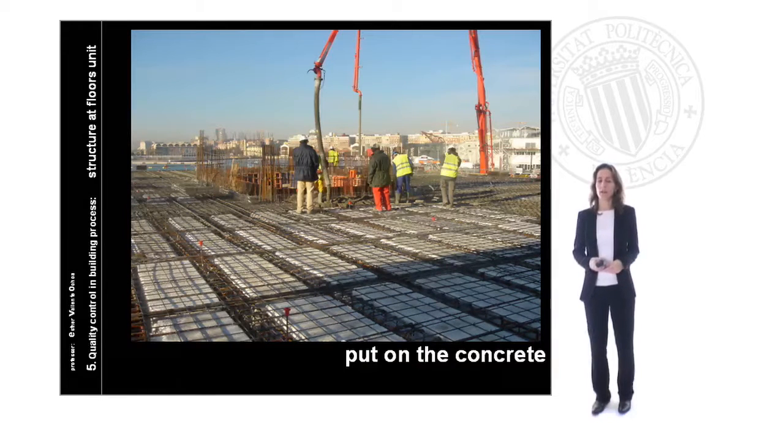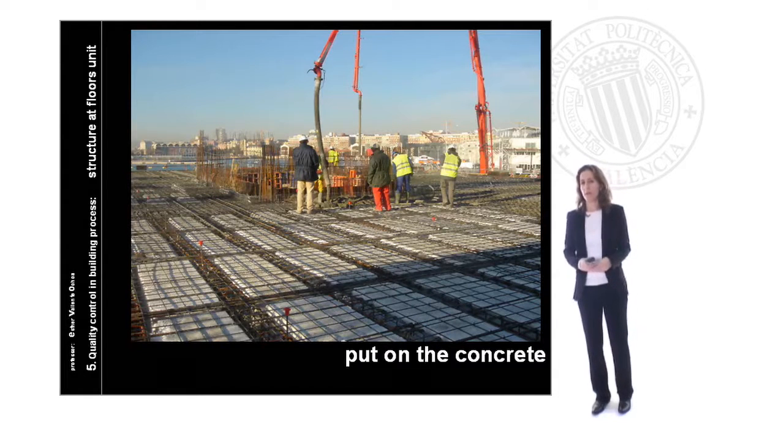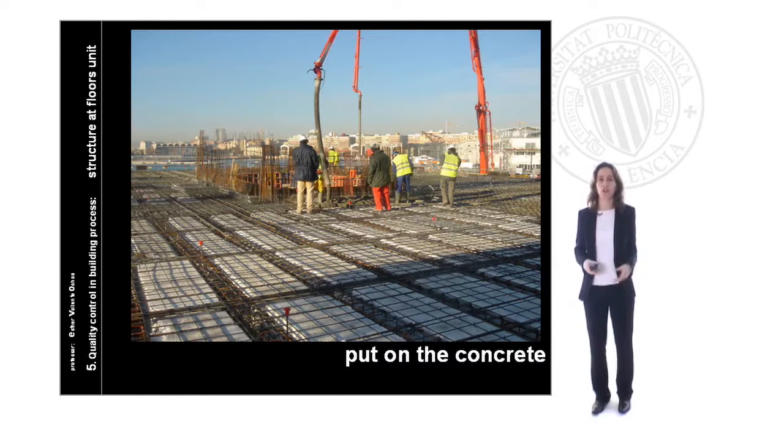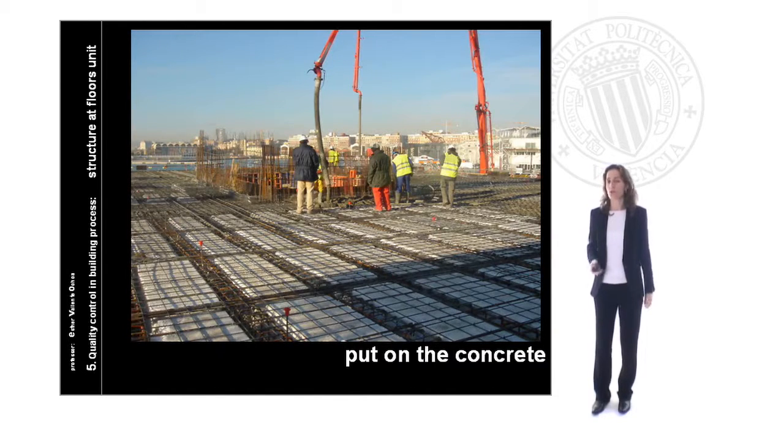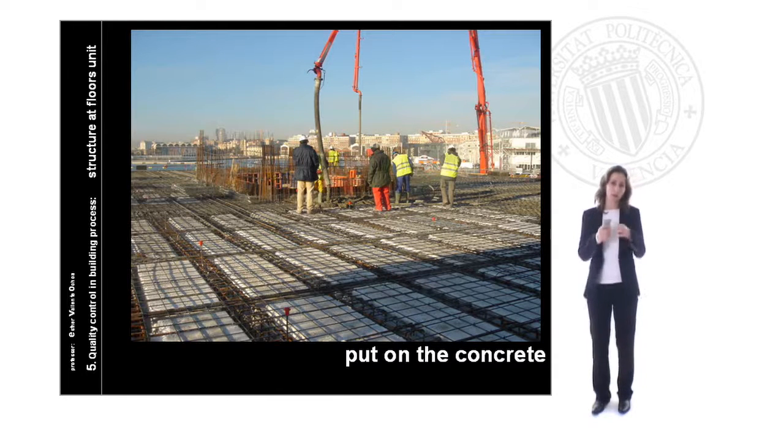It's recommended to concrete the floor in one day. If it's possible, don't try to make joints and just concrete in one day, in order to be sure all the surface has the same concrete with the same age. Also control the maximum height from which the concrete is poured onto the floor, so it is not dropped from high levels, because the contents of the concrete will be crushed.